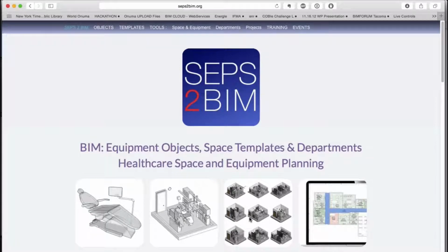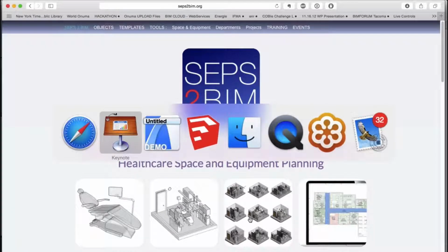Obviously, it's going to shift a little bit, and that variation depends on the owner's tolerance of how much delta they want, but once you have data in place like that in BIM and in a database like this, you can start doing a lot of crunching and analysis of the data and reports. Also, having the data outside of the model allows a lot of other non-BIM users to interact with it. So the COBie export that I talked about earlier, you don't have to have a BIM to start interacting with the model. You're seeing room data that you can start making decisions on.